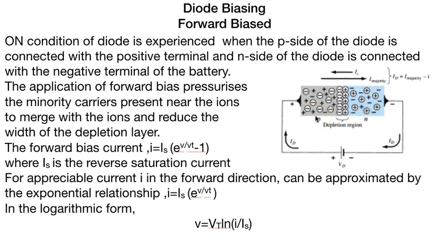In the forward direction, we'll see that the majority carriers move from the plus side of the region to the minus side. And as we have talked earlier, in forward direction, the depletion region shrinks. It doesn't expand, but it shrinks. And the potential developed across this depletion region is subtracted from the actual circuit diode voltage. So this was the major analysis of a PN junction diode.